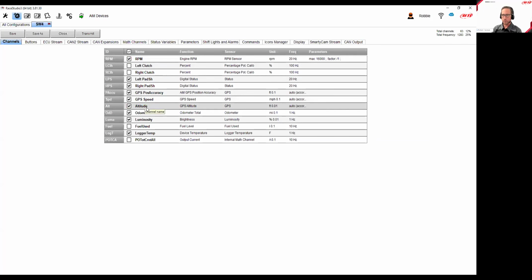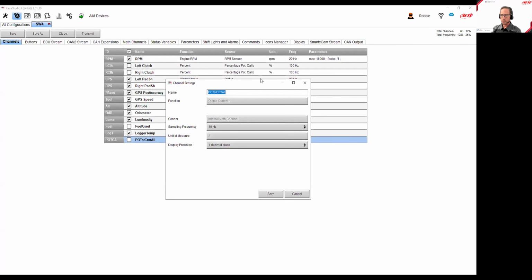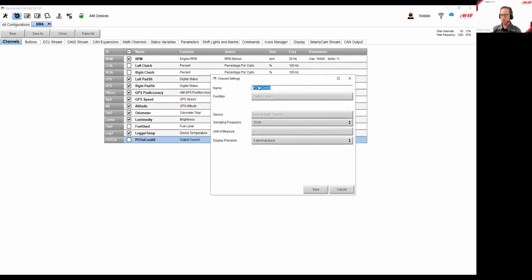So in this situation, we have the clutch systems, the potential total current. This one here is only available if you select an EPM, and it will allow you to control or record how much total current that EPM is pulling from or distributing out into the vehicle. So it's an aggregate number. It takes all of the 32 power outputs and combines them together and says this is what it costs to run this EPM. So now you can pair it against your alternator and see if you're going to be consuming more than what you're able to produce.